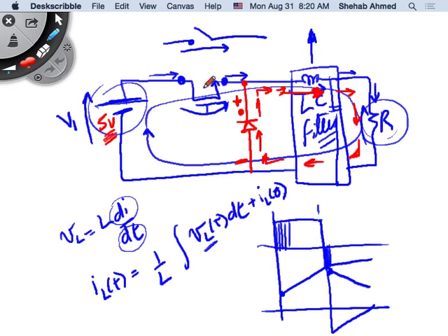So during this transition from the diode being on to the diode blocking. Remember, as soon as the MOSFET turns on, the diode will block. Correct? So during this transition, we said that this diode characteristic is a bit special, right? It was conducting current, and then when this MOSFET turns on, it will stop conducting. Fine. During the transition, there's something else that happens. It was conducting current, but as soon as you apply voltage, it wants to start blocking.